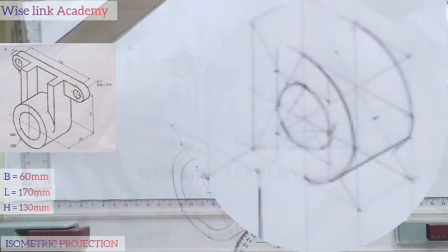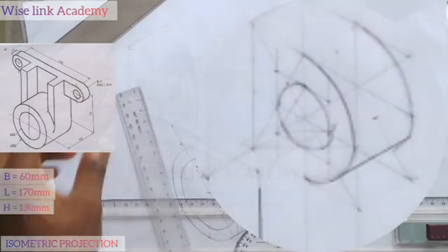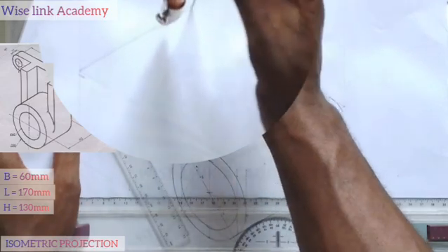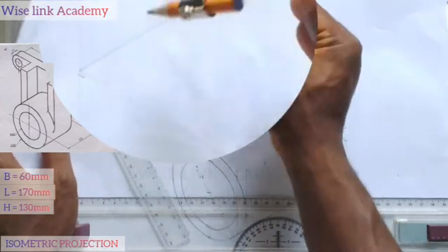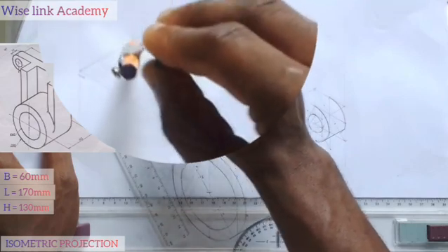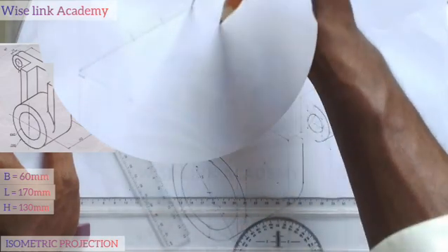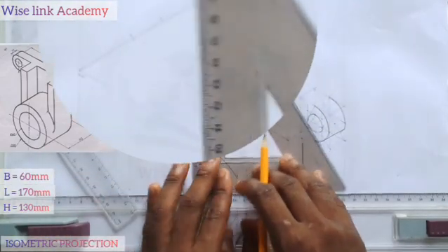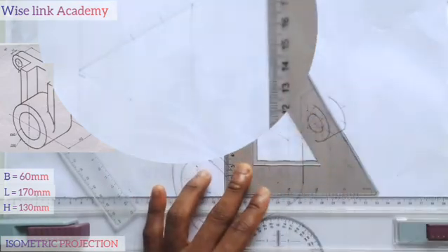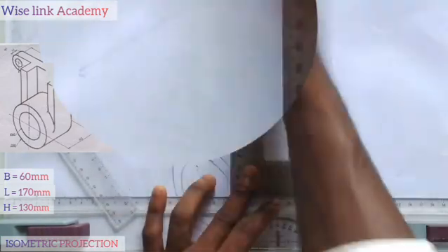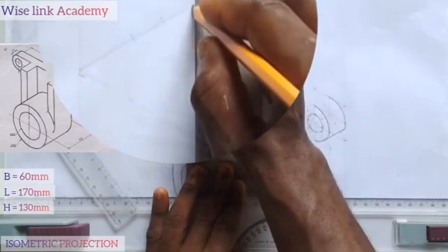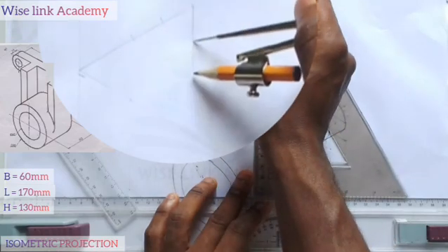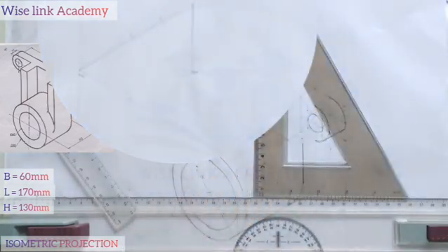So I'll take my meter rule also, measure 15 as we did initially. At this point here, right? Take an arc 1, also 2. At this point here again, take it 1 inward, 2. I'll take my set square this way. At this edge point, take it down this way. Come in. I'll take this edge point down this way. I'll also measure 15 from this point here, 1, also 2. As you can see what I'm doing.